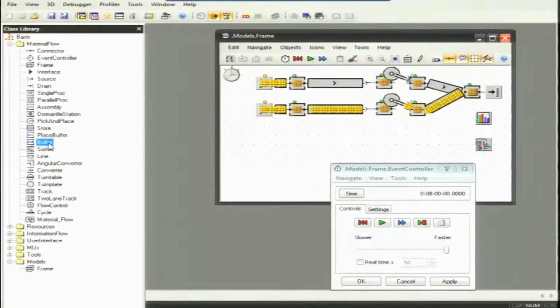Place buffer is a small thing; the big buffer is placed between two plant components for certain purposes. It temporarily holds parts when the following components fail, when the successor is not able to receive the component. The second important function is that it passes the part on when the preceding components stop working. It has the dimensions of a buffer with large enough capacity for covering all failures, which leads to complete decoupling of the plant, and the other attributes as well.